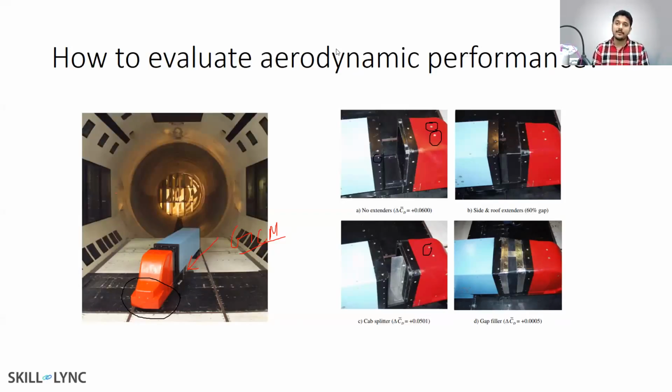You need to validate your CFD code, and then based upon the validation, you can figure out that, okay, if I'm able to validate an external flow problem at this Reynolds number, then for that same Reynolds number, if I modify the geometry, most likely I'm going to get the accurate answer, or most likely I'm going to get a very close answer. That is why this is being done.